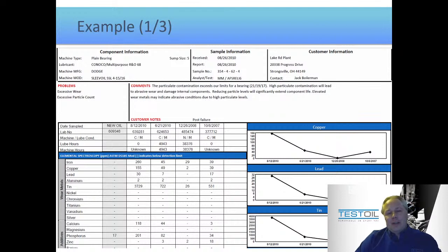So once we start into the oil analysis data section, we look at the data here and we see one of the first things that comes up is, wow, that is really, really high iron. But is that a cause or an effect? Well, again, wear is usually just an effect. Something is making it wear. So why did it fail? Well, we'll have to keep reading. So we'll just log iron down as an effect.